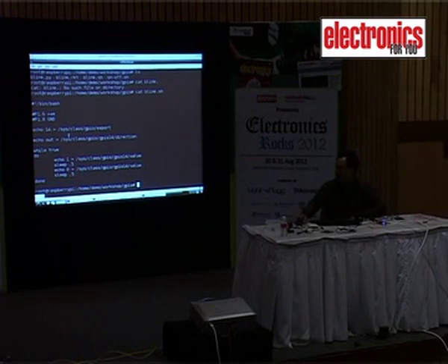Basically, you are writing values 1 and 0 to a special file, a file under the folder sys/class/gpio/gpio14. GPIO14 is the I/O pin number of the pin to which I have connected the LED here.